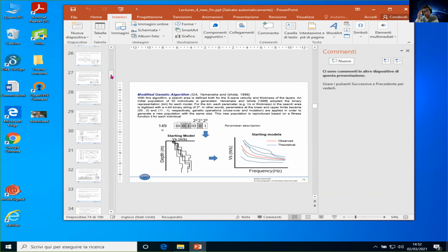So when we are doing the inversion, we are calculating the difference between the observed and the calculated from the assumed model. So we take the phase velocity versus frequency branch as just one branch, either for the fundamental mode or some other. You can do two things. You can have an inversion if your curve is only for the fundamental mode, for example. Then you can make the inversion only for the branch for the fundamental mode. Or you can also perform the inversion using different modes.